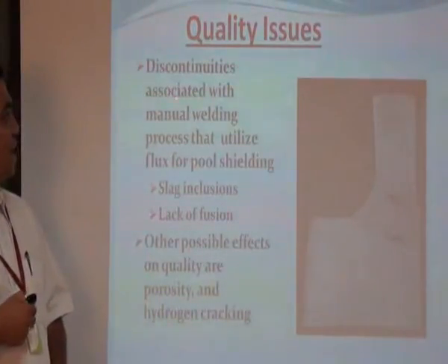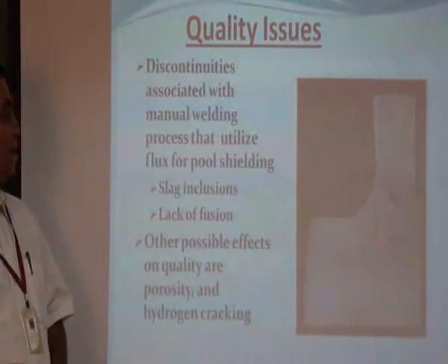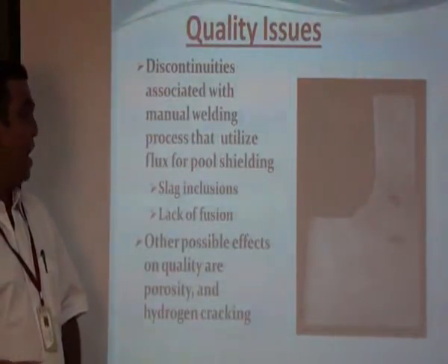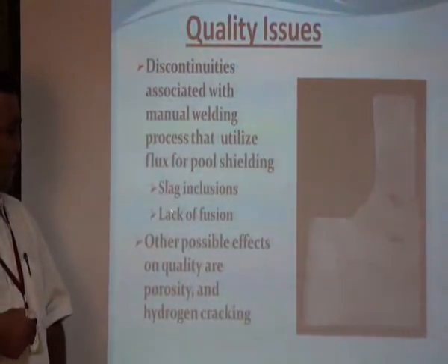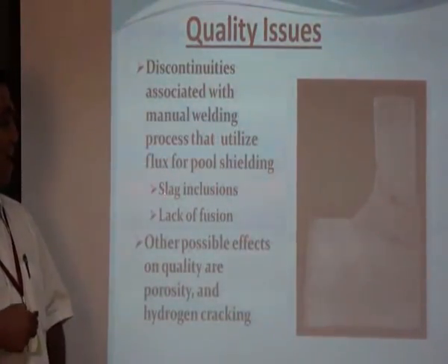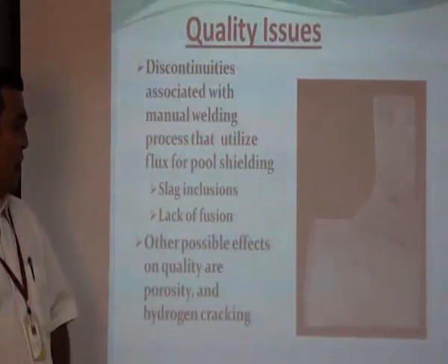The discontinuities are associated with manual welding processes that utilize flux for shielding, and the two common defects caused by this flux are nothing but slag inclusions and sometimes lack of fusion.